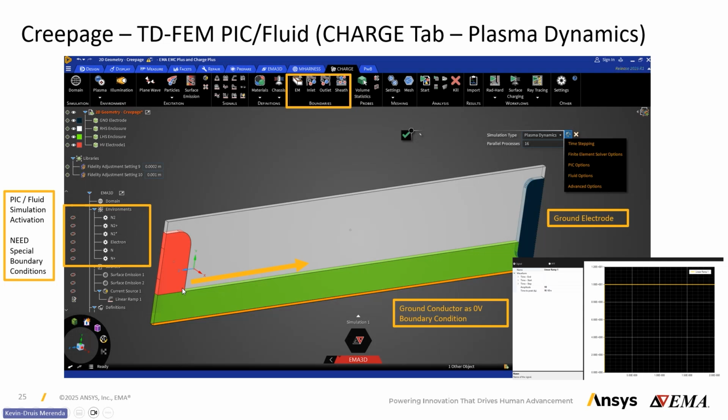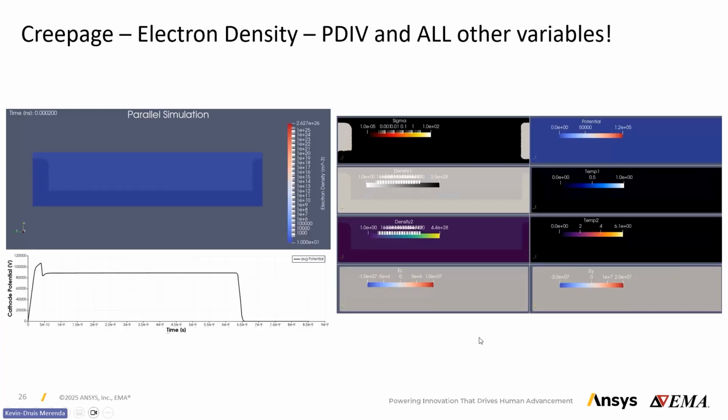There is a field enhancement due to the ground backing under the electrode, but there's also a triple point junction here that will have field enhancement and a higher chance of discharging. So we expect the discharge to really happen from the electrode, given its geometry and the field enhancement in that location. I'm applying 10 amps onto this location, and this will just drive current flowing through the system over time.